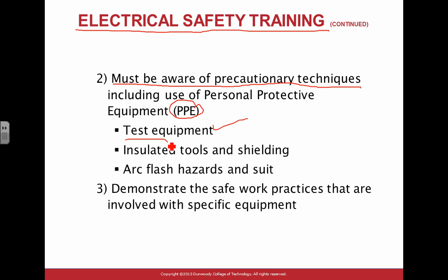Well, it really goes by the energy. Typically, if you're working on a 20 amp, 120 volt circuit, this meter will take care of you. So 120 volt AC or DC control circuits, where the circuit feeding the control circuit is 20 amps or less, this is adequate for you. But if you go to a 100 amp, 3-phase circuit and you're verifying the voltage on the line or the load side, that's what you need to do.